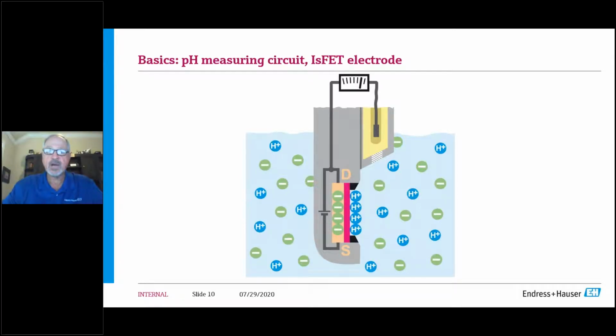And it's just as reactive to the pH changes as a traditional electrode. How it works, however, is it still has the same electrochemical reference internal with the silver chloride and the potassium chloride conducting fluid, and then it has a little porous membrane.